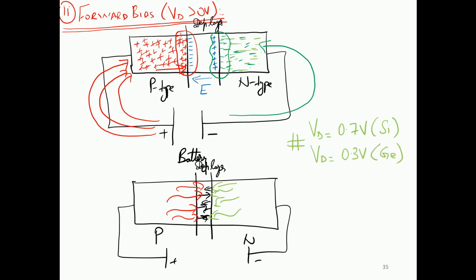So these are the magical values that are most of the time going to be utilized in this course. Whenever the forward bias voltage Vd reaches a value of 0.7 volt if the material is made from a silicon semiconductor, or it reaches a value of 0.3 volts if the material is made from a germanium semiconductor, the current is going to flow. Even if the barrier doesn't shrink enough, but it has become reduced from its previous value, the current is going to flow from here to here, the conventional flow from the positive to negative.